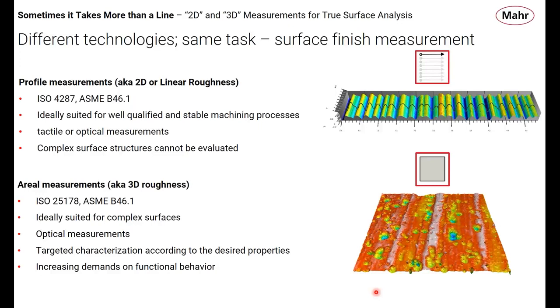We can look at our RA value and say, oh, RA is climbing, it must mean we have some tool wear, time to replace some tooling, or our feed rate must be off, or RA is dropping, the laser must be too hot on the welder. So these very simple things, we can look at RA and we know exactly, from our 50 years of experience with this process, our 100 years of experience with this process, when RA does that, we need to go look at this.